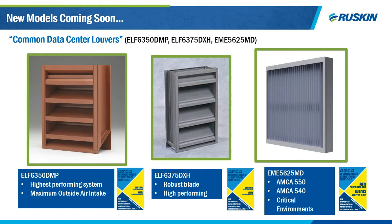So starting with the ELF 6350 DMP, it's one of our highest performing louvers because of its drainable blade design that actually channels water down the jamb gutters and out the front of the louver. This design provides excellent water penetration, and coupling that with its exceptional high free area at 62%, it is one of the most top specifiable models for louvers out there for data centers.